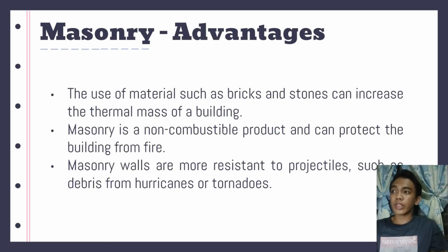Now, for its advantages, the use of materials such as bricks and stones can increase the thermal mass of the building. And masonry is also a non-combustible product, which means that it can protect the building from fire. That's why some or most of the residential buildings are building firewalls.